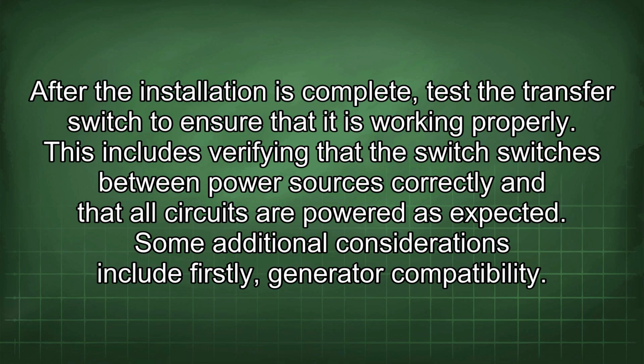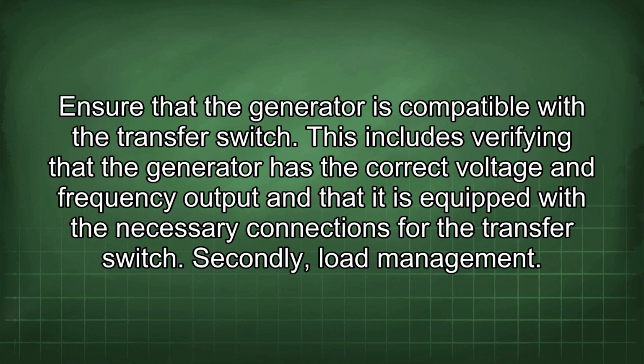Some additional considerations include, firstly, generator compatibility. Ensure that the generator is compatible with the transfer switch. This includes verifying that the generator has the correct voltage and frequency output and that it is equipped with the necessary connections for the transfer switch.